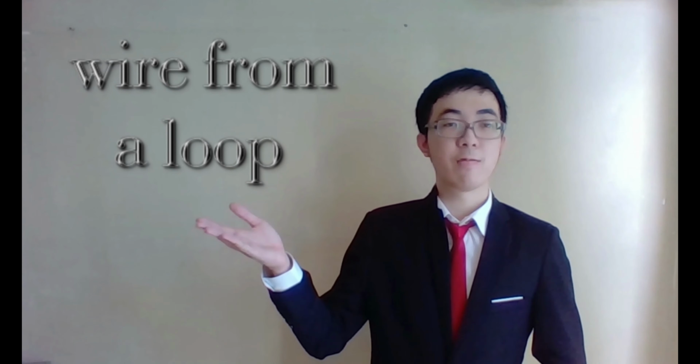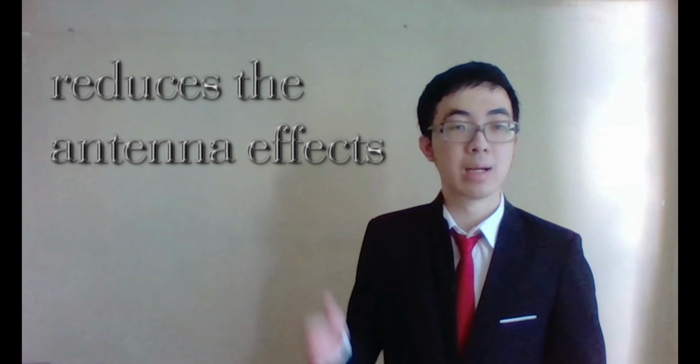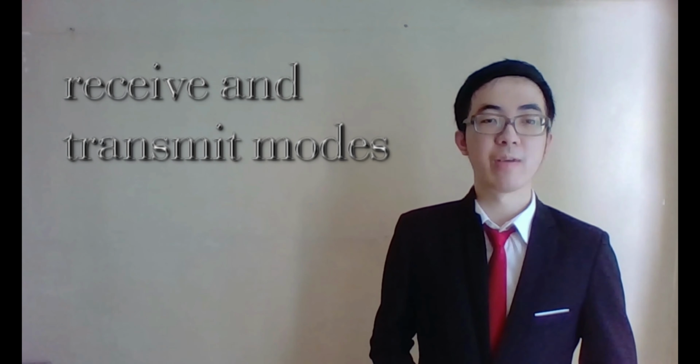Besides, wires form a loose and efficient antenna, which causes EMC problems. The efficiency of any antenna can be optimized by the length of the shaft of the antenna for any given frequency. A good practice for minimizing the ability of an antenna to send or receive is to minimize the loop. Run the feed and return wires together rather than allowing a loop to form. Twisting the pair together further reduces the antenna effects. This also applies to potential wiring. Antennas work equally well in both receive and transmit modes.